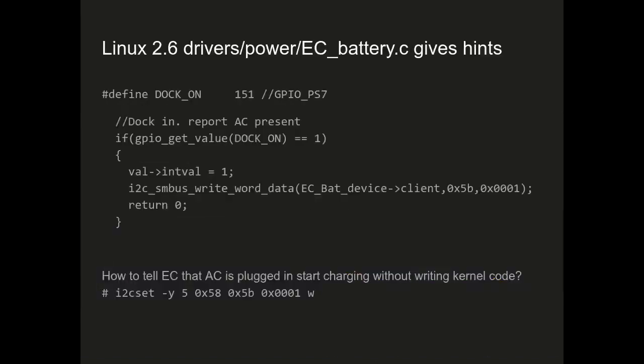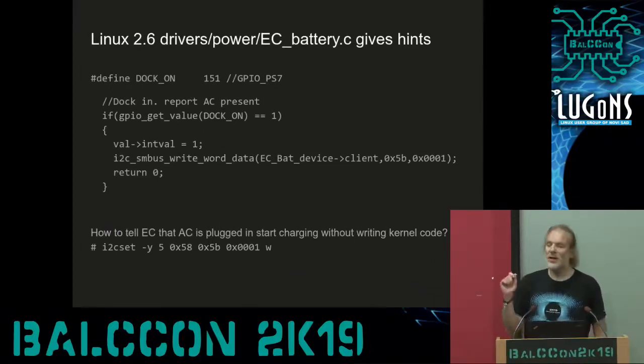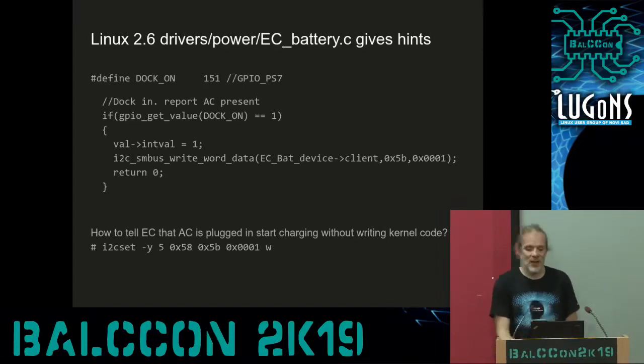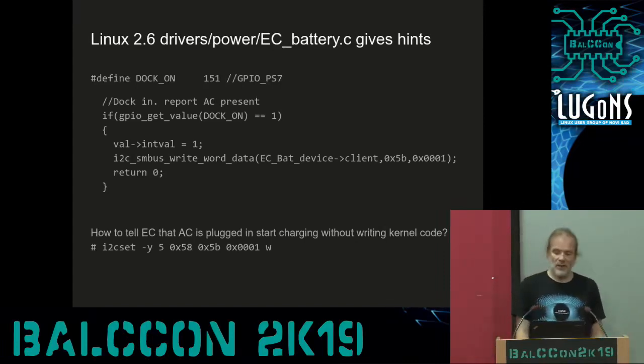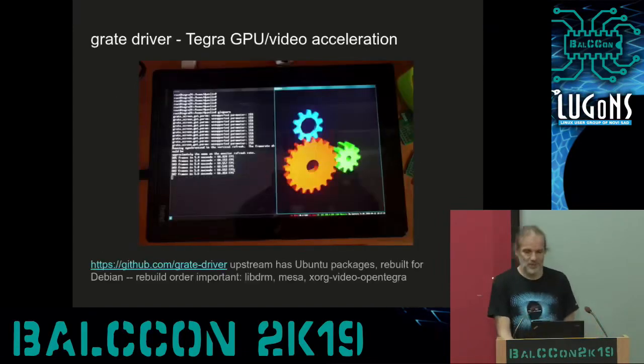After a lot of machinations and looking in the source code, I actually found the place in which they trigger the BIOS controller over I2C, and I was able to replicate that on the command line, which is this i2cset on the bottom, and I got my charging back.